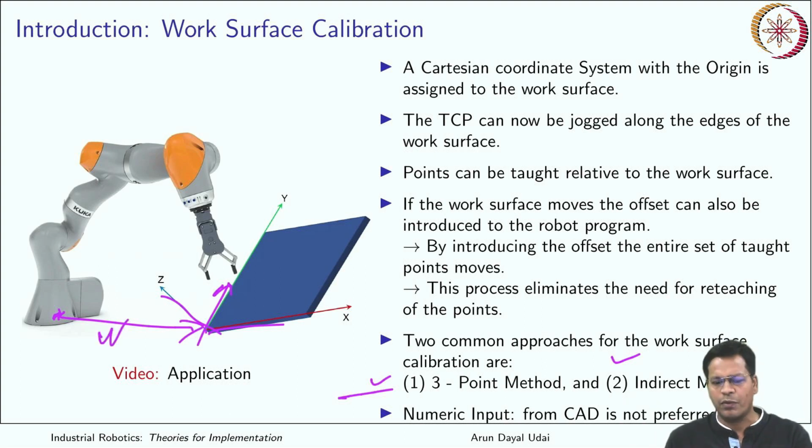Even a small amount of error will cause your robot tool tip to hit that surface. Okay, so that is quite probable because this is long and your error is relatively smaller with respect to this distance, but it may be quite big as far as your robot's accuracy is concerned. So it can hit that. So it is not advisable in case of this.